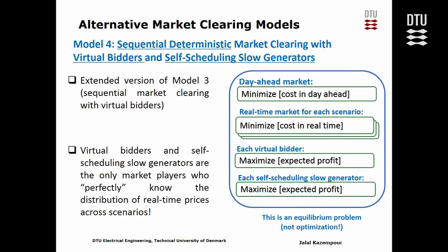So, we derived these KKTs. We use unit commitment, so our optimizations originally have binaries, they are mixed integer. Then we relax the binaries between 0 and 1. We can argue whether it is better to totally ignore binaries or have the binaries but relax them.